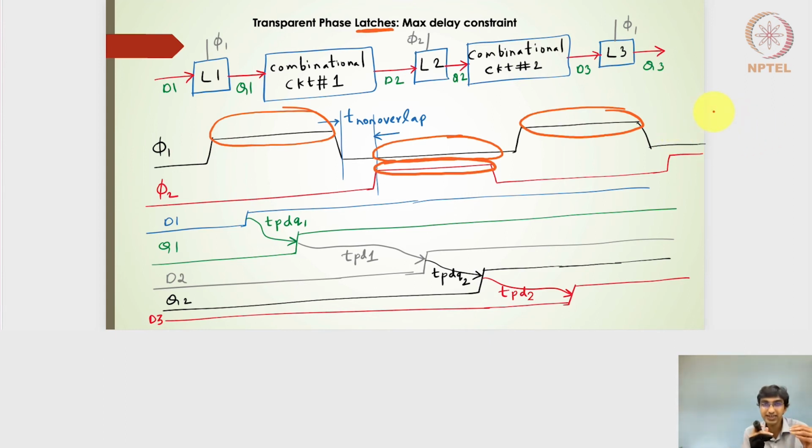So the difference between latches and flip-flops is that flip-flops operate only on the clock edges, so we make sure the combinatorial circuit's output is captured in the subsequent clock edges. Whereas here, because of the latch design, we have the ability to have a faster combinatorial circuit captured in the positive levels as well as the negative levels of the clocks, right?